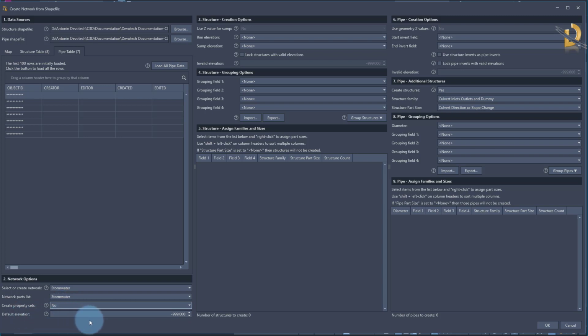And if there is no elevation in the shapefile, it will use a default elevation of -999. So you can clearly see in 3D view if any entities do not have a correct elevation. Or if you don't want to use such a high value, you can go, let's say, to 0. But keep in mind that some services can be at a 0 elevation, because if you are close to the sea level, there might be entities at a 0 elevation. Some shapefiles do contain that elevation, and if they do, you can use it if you wish to. This shapefile doesn't have it.